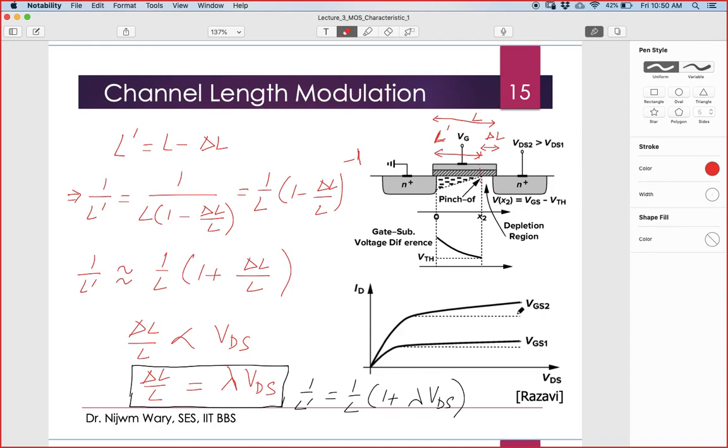It's not constant, it's increasing. And if my channel length is very small, this pinch off is becoming significant, this delta is becoming significant. So in that situation the current is increasing more. Did I answer your question?